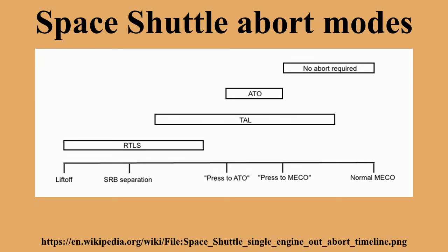The struts attaching the orbiter to the external tank were strengthened to better endure a multiple SSME failure during SRB flight. Loss of three SSMEs was survivable for the crew for most of the ascent, although survival in the event of three failed SSMEs before T+90 seconds was unlikely due to design loads being exceeded on the forward orbiter/ET and SRB/ET attach points, and still problematic at any time during SRB flight due to controllability during staging.